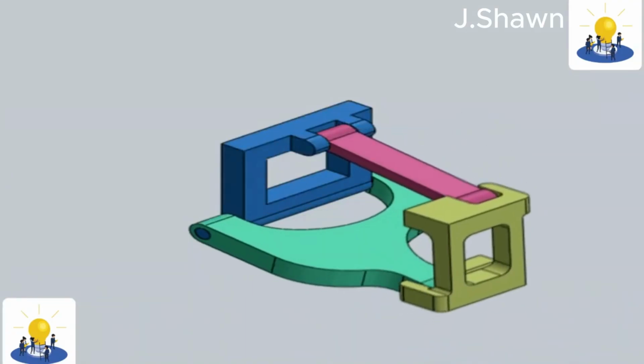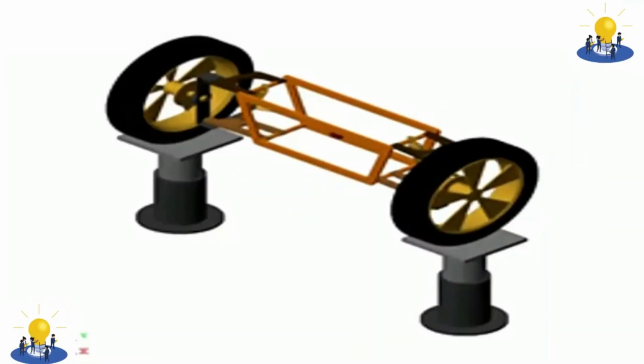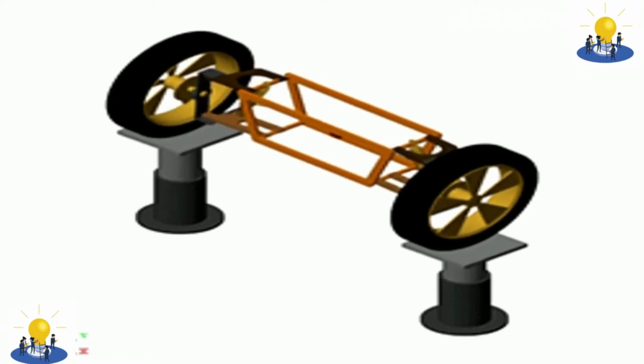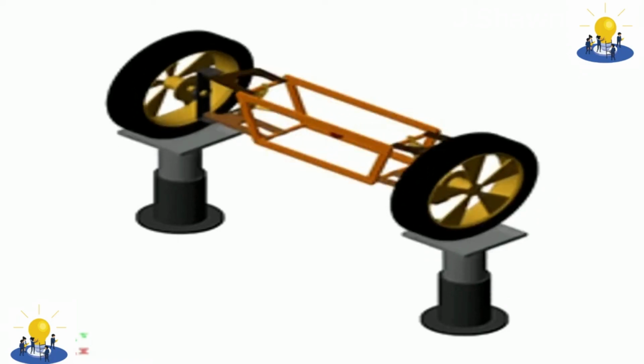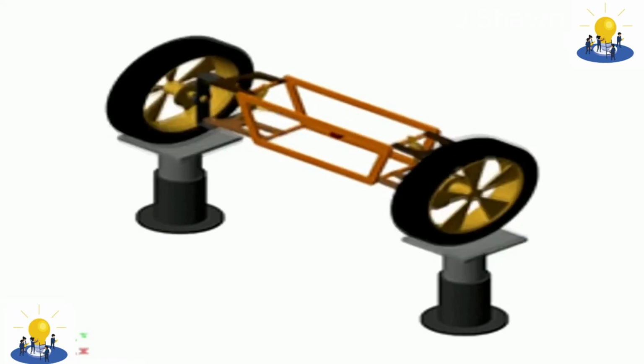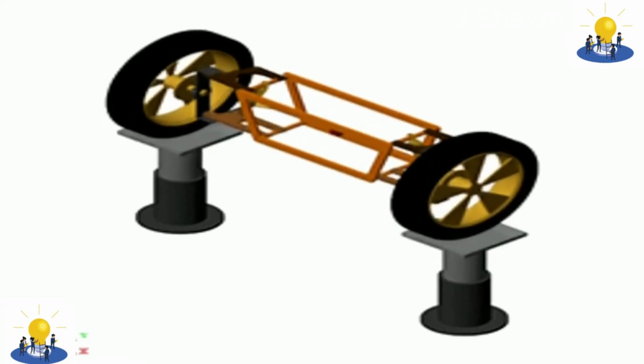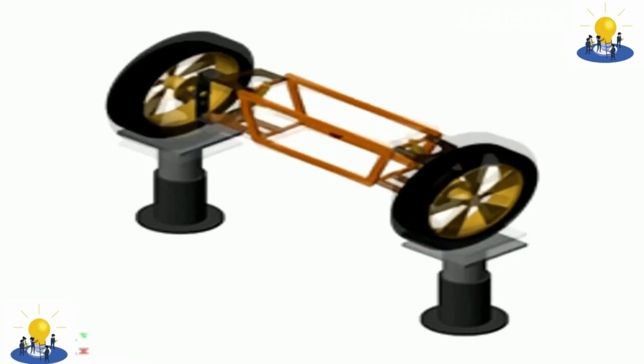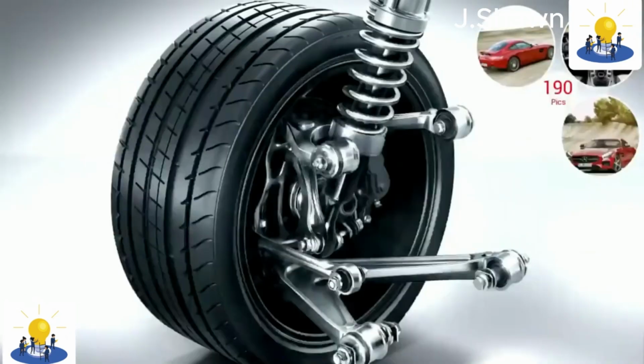The opposite arrangement, a pull rod, will pull on the rod during bump travel, and the rod must be attached to the top of the upright, angled downward. Locating the spring and damper inboard increases the total mass of the suspension, but reduces the unsprung mass, and also allows the designer to make the suspension more aerodynamic.